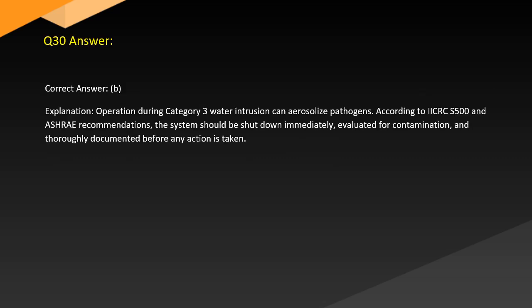Answer. Correct answer. B. Explanation. Operation during Category 3 water intrusion can aerosolize pathogens. According to ICAC and ASHRAE recommendations, the system should be shut down, immediately evaluated for contamination, and thoroughly documented before any action is taken.